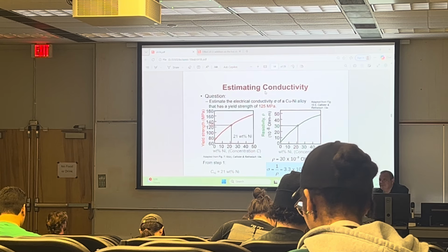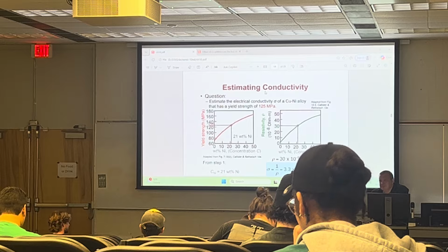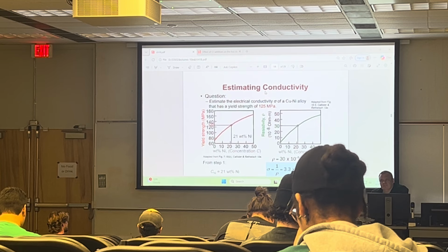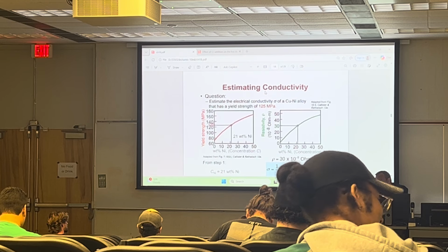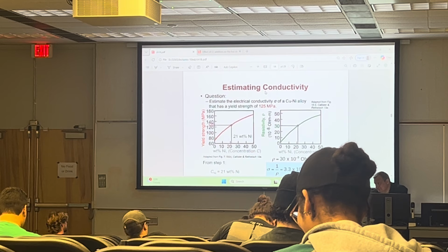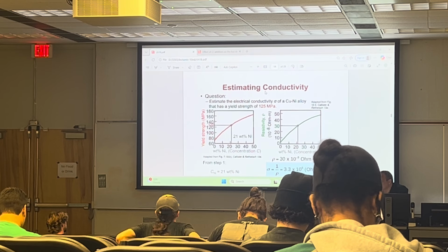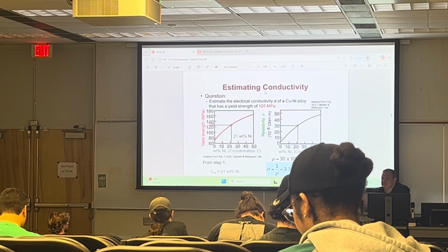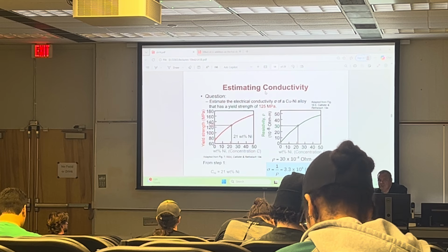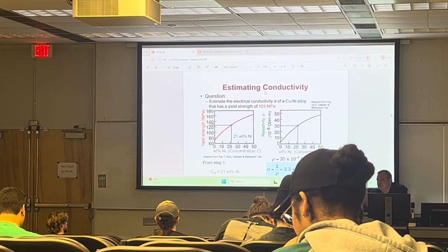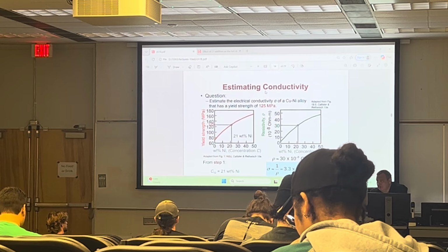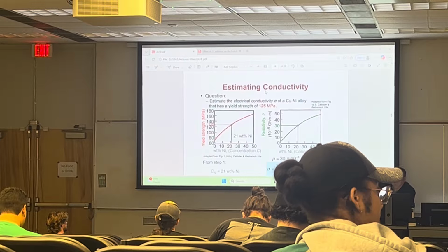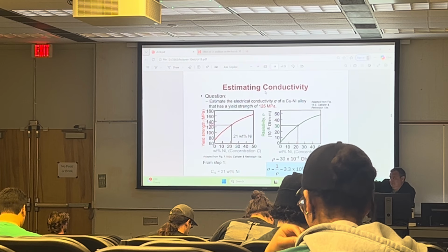What is yield strength? No. Let's get to it. What is the yield strength? It's the strength at which the material, yes, yields. Okay, so you want to avoid that. Why? Because after you deform the material into the plastic region, it relaxes and it's not keeping its original shape. It becomes longer. You don't want that. So it did not physically break, but imagine the wire that's hanging along that train that's going 300 miles an hour. You get the point.